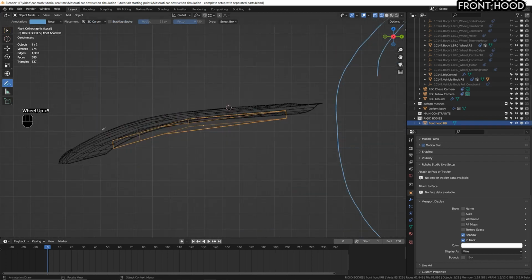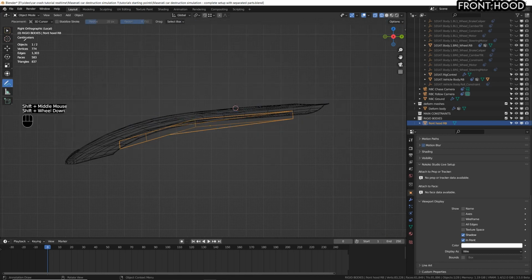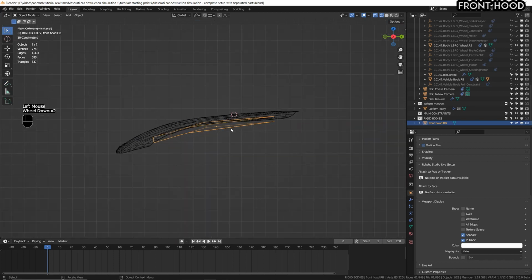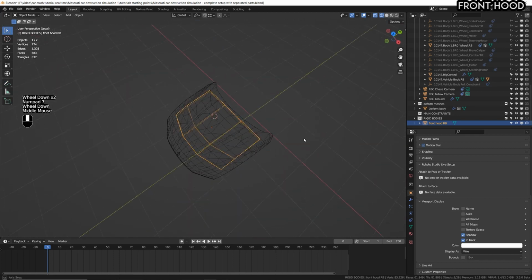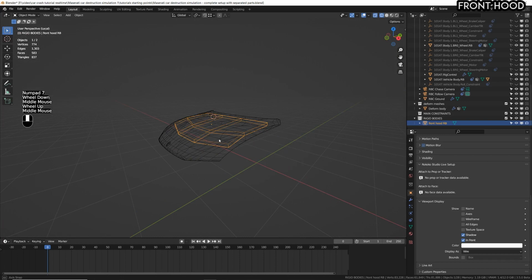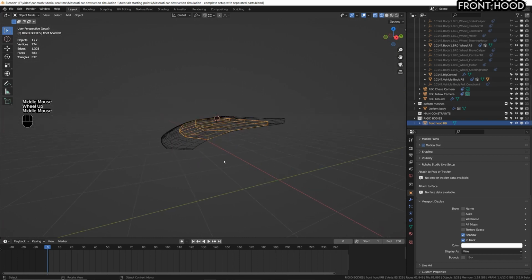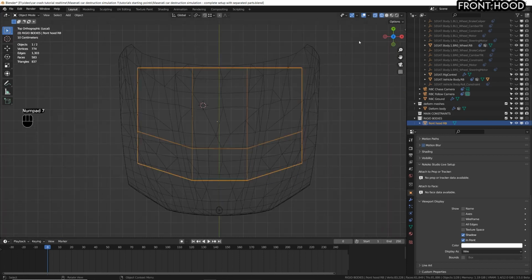Instead, in this case, the mesh deform modifier is not gonna work because when the displacement is going to happen, this top part is going to displace, going down like this, and instead the part in the bottom is going to go up like this, generating self-intersections. And for this reason, I'm going to use a little bit different system. So as a deform mesh, we are going to use a flat plane, and instead of using the mesh deform modifier, we are going to use the surface deform modifier. I'm going to explain more in detail now.